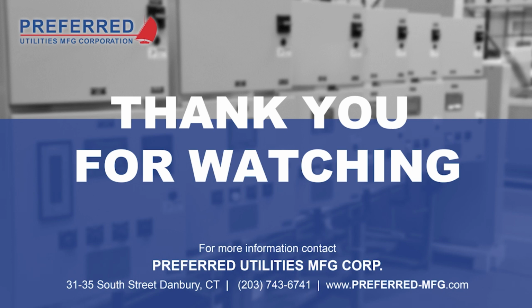Let's see, we got another question here. If I'm getting multiple flame fails during PTFI, what could be happening? Well, there's a variety of things here. Obviously, during PTFI, if, for instance, the fuel pressure on the pilot assembly is just not quite high enough, that could be causing it to not light properly.